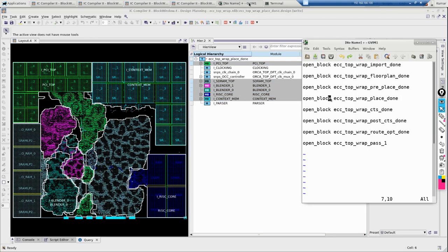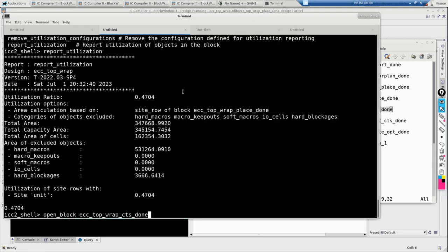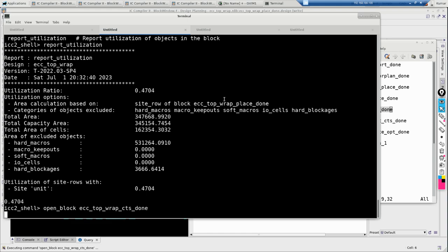And then your standard cells which were sitting at 0 0 have now all been brought in. Now you are analyzing in terms of timing, congestion, and utilization. And then the next step is to look at your CTS clock tree. So we would go and build your clock tree and see.